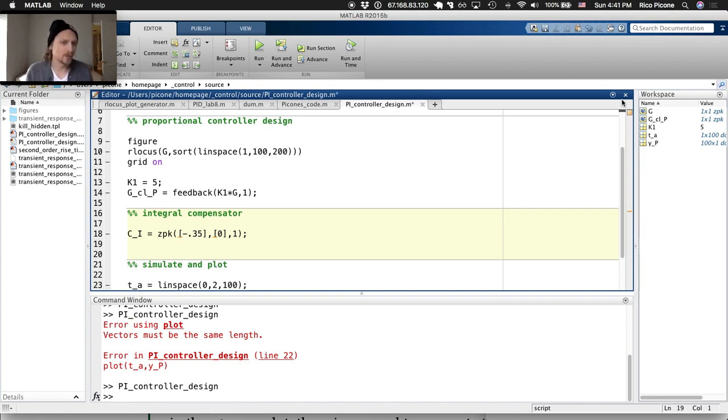So we could do another root locus. One way to go here, we have a new compensator, could do a new root locus, could choose our 20% overshoot again. It's really up to you at this point. If you want to do another root locus, that would be good. Another thing we could do is just try it and see what the simulation looks like. So I'm inclined to do that.